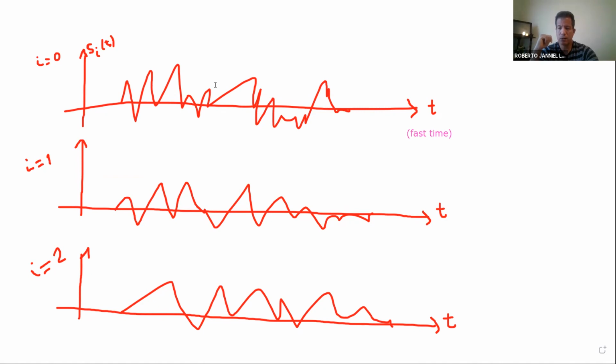Because my signal is oscillating in the range of megahertz, which is the microsecond range. So actually, that's very generous of you, but it's actually milliseconds, for reasons that will probably be more apparent afterwards. So the PRF typically ranges in the kilohertz. So we're shooting out the transducer over and over, much slower than the megahertz that I'm using to sample the signals in the time domain.